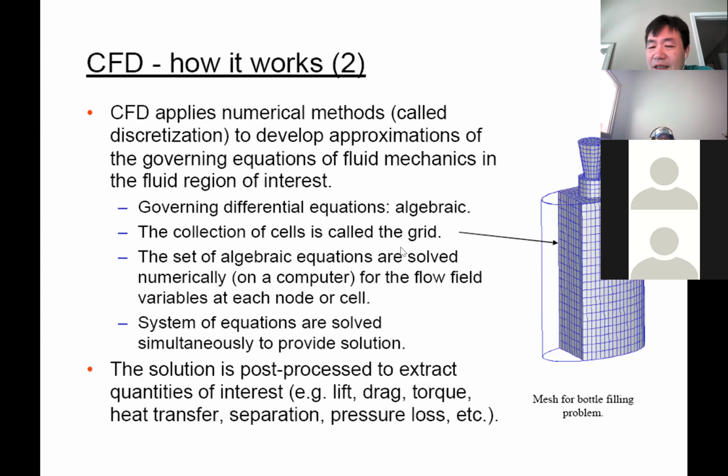After you draw it, the next step, very important, is to place mesh or grid on the volume that you're interested in, on the space that you're interested in, which in this problem is the tank, also a little bit of pipe or nozzle here, where the flow gets injected into the tank. So place your mesh.